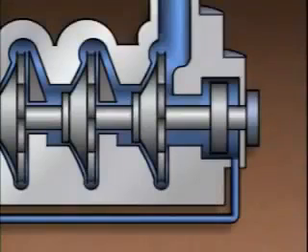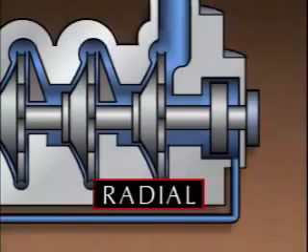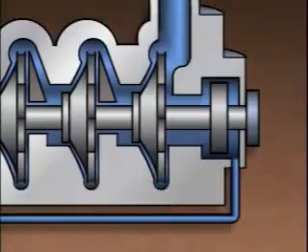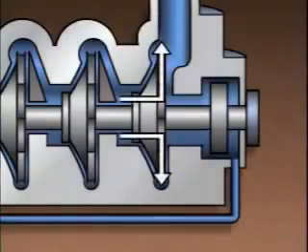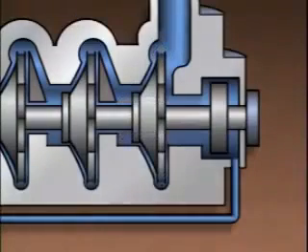One way that centrifugal pumps can be categorized is by the way liquid flows through them. Three common flow path classifications are radial flow, axial flow, and mixed flow. In centrifugal pumps that have a radial flow design, the impeller causes the liquid to make a 90-degree turn and flow outward, or radially, from the suction eye to the tips of the vanes. A radial flow pump takes advantage of the maximum amount of centrifugal force that the impeller develops.